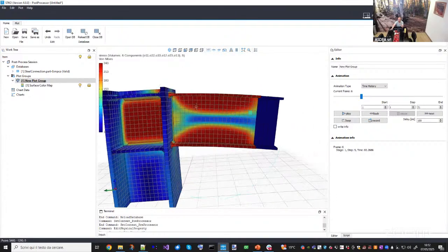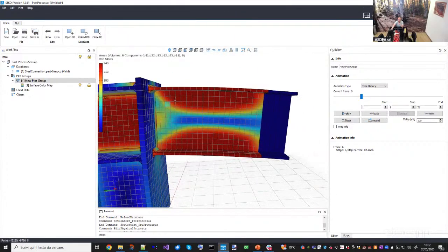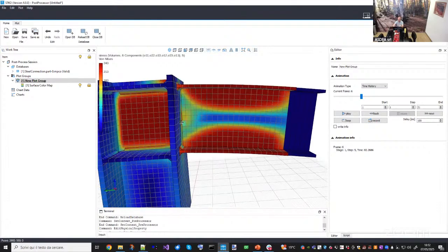Of course, notice that here it makes sense. I'm applying cylindrical bending, so only an applied couple. So the bending moment should be constant through the beam. Of course, here it is not because of the connection, but when you are far enough from the end zone, the beam solution applies.